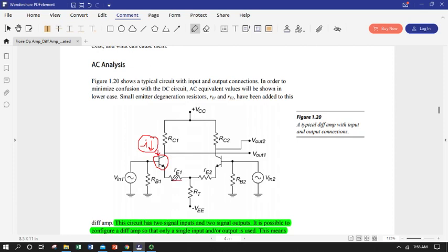What's important from our standpoint is our emitter resistor, our little RE, that we needed our collector DC current to get. Remember, using our Q point to evaluate this using our diode equation. So that's why we started with our DC model. But one thing we can look at with the circuit drawn this way with our signal inputs is we can notice we have a lot of choices. If we just had a single BJT in a small signal amplifier, we could put a signal in one place and get a signal out another place.